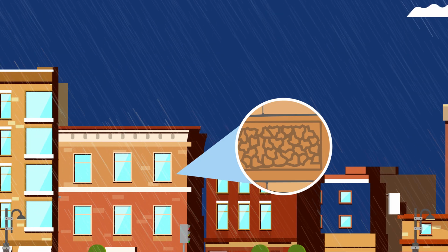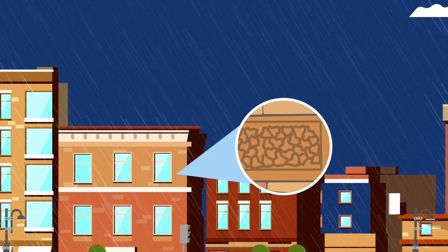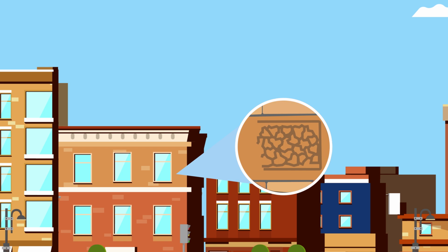In stones that are initially expanded and then dried, this can lead to damaging tensile stresses, causing cracking perpendicular to the exposed surface. Tensile damage mainly concerns finials and decorative elements because they can easily become saturated with water.